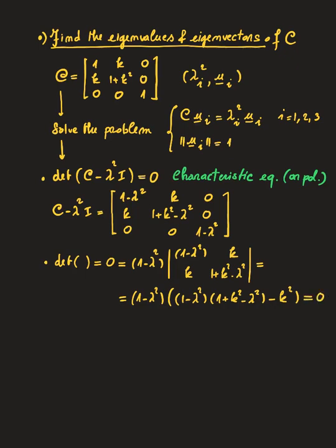If you expand this expression, it is clear that this is, in fact, a sextic equation, but remember that each of these lambdas has to be positive. Why? Well, lambda in general expresses a ratio between a deformed length and an undeformed length, so clearly you cannot have negative solutions, because negative would mean that you have essentially annihilated matter.